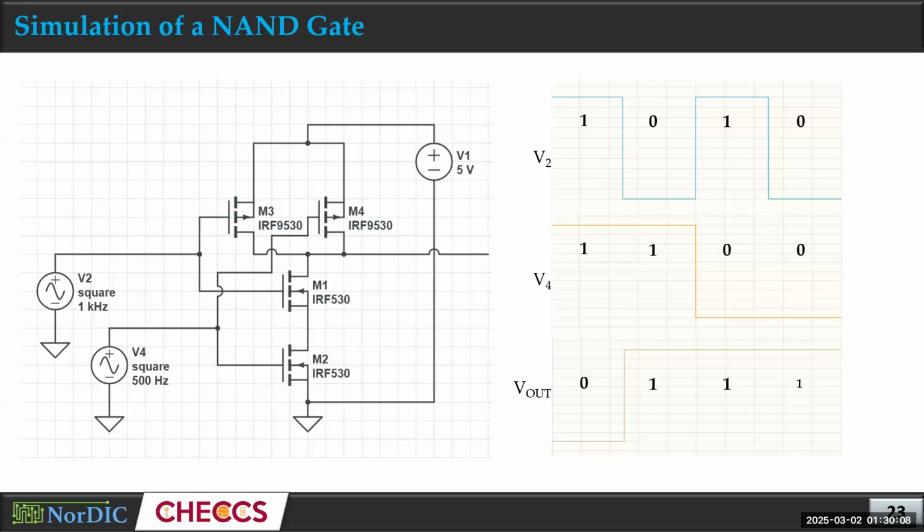Yeah, like that, right? But if you check the design rule, there will be an error because there is no minimum separation, so you have to move this as well. Then you have to align this with this one, and this one with that.